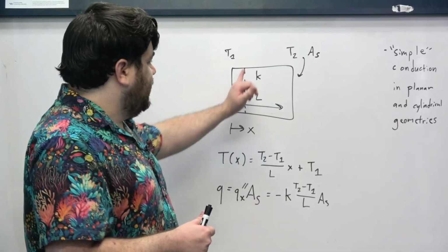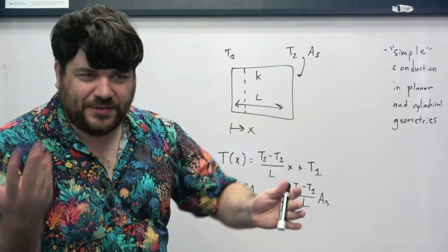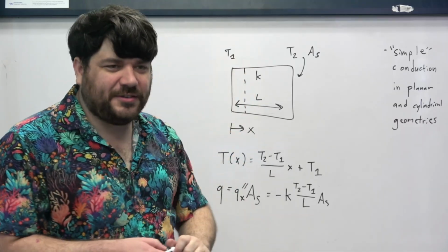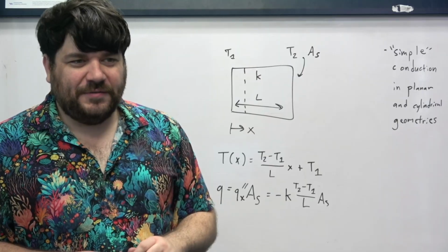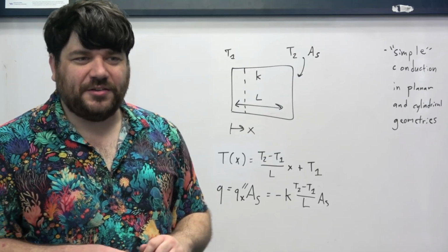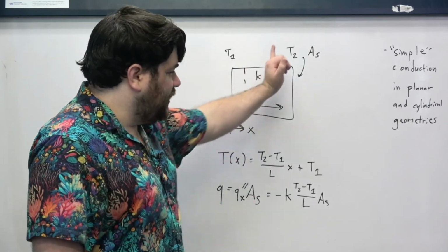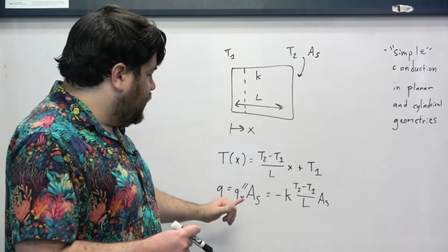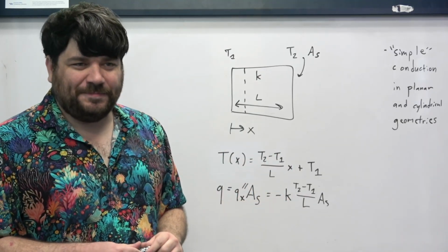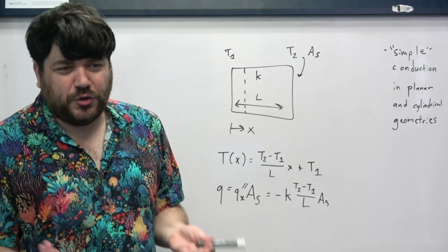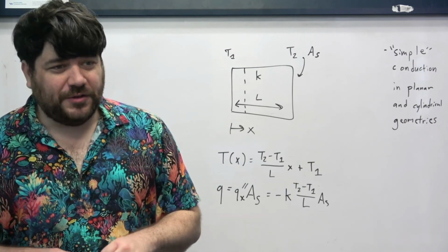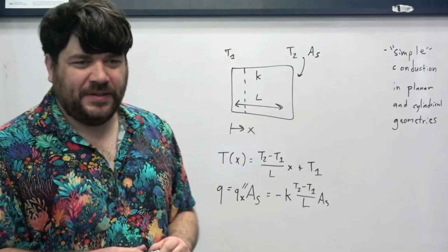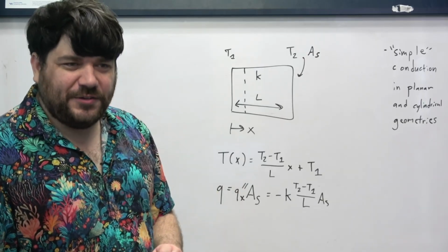So the heat flux not only doesn't change by assumption over any region in this cross-section, but it also doesn't change depending on whatever value of x you're doing your analysis in. So it doesn't matter that I cut my section here or here, I'm still going to get the same value of the heat flux. And so ultimately heat flux is conserved, so to speak, in planar systems where all of these assumptions are valid. All right? So this is the story for planar systems.